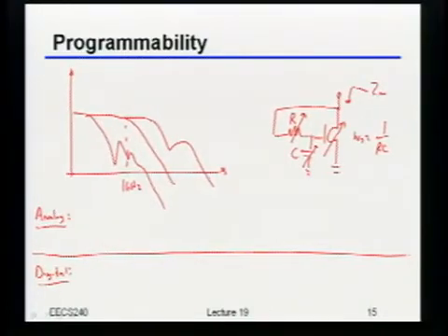So, for the analog, let's say I wanted to tune the resistance. Well, that's perhaps obvious. I could just take a transistor in the triode region, and move the gate voltage around in an analog way, so effectively I'll be tuning that resistance with the gate voltage, right?